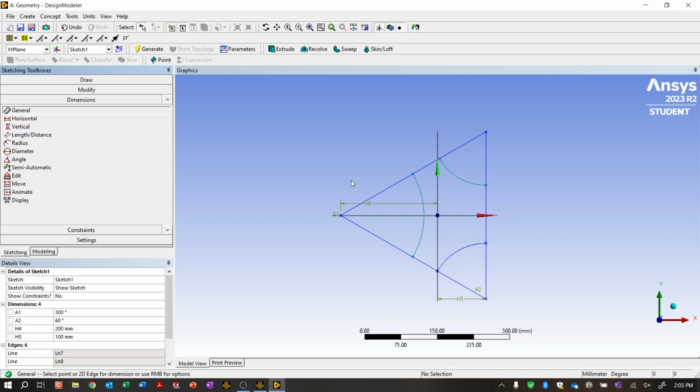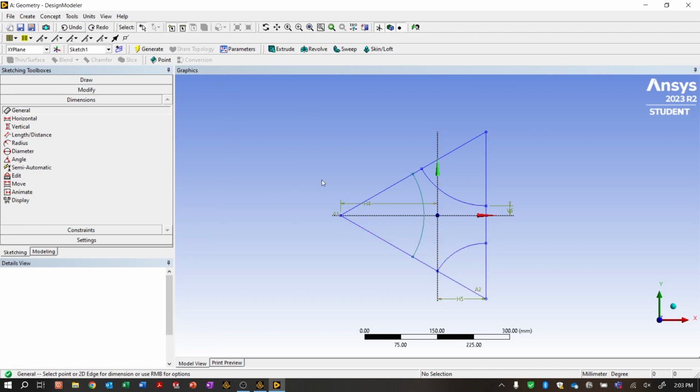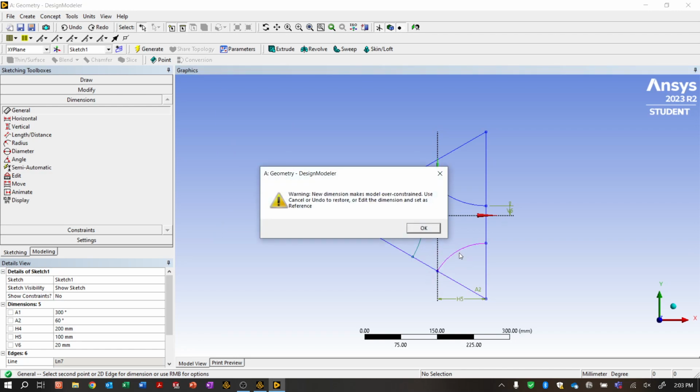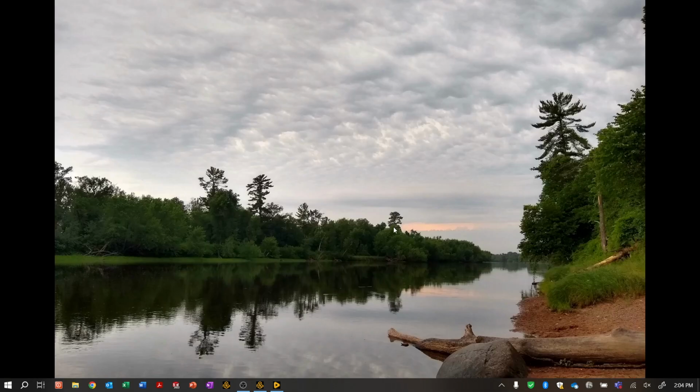So looking at the figure, each one of these little angled lines, the flat parts of this triangular plate, are supposed to be 40 millimeters wide. So I'm going to set this here at 20. I'm just typing that down in the dimension box, and then I'll do 40 from there to there. Oh. Yes, so it did think I wanted this to be constrained on this line, on the axis, so I need to get rid of this guy. Oh, I don't want a dimension. Oh, that's exciting. Sorry about that.